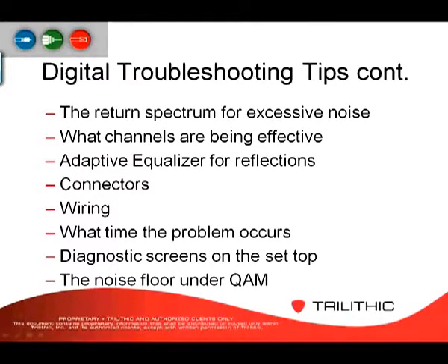Check your connectors, making sure your connectors are nice and snug, because that's one of the biggest problems that I run into when I'm looking in the plant: loose connectors, and that will cause you a lot of problems. Make sure that the wiring is proper, and then verify what time the problems actually occur.